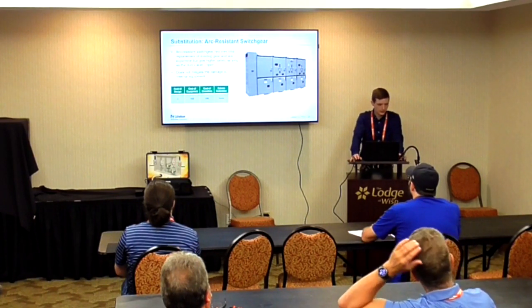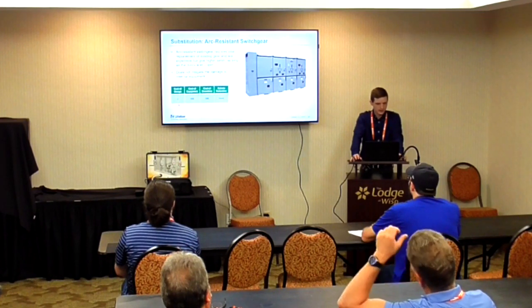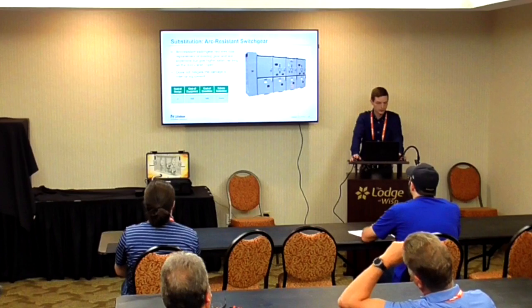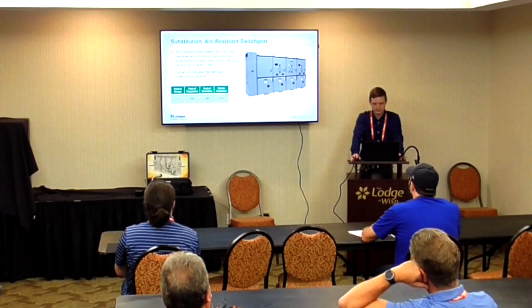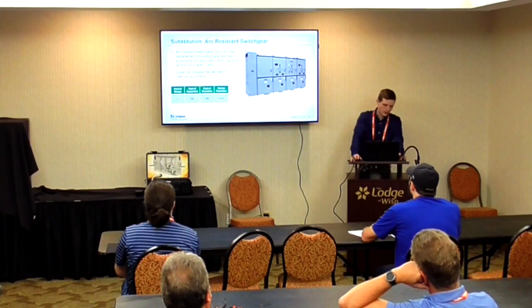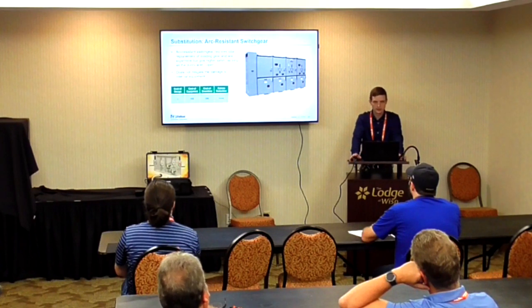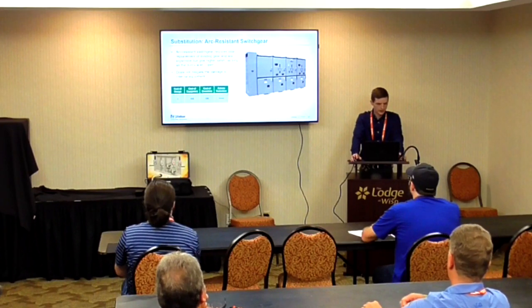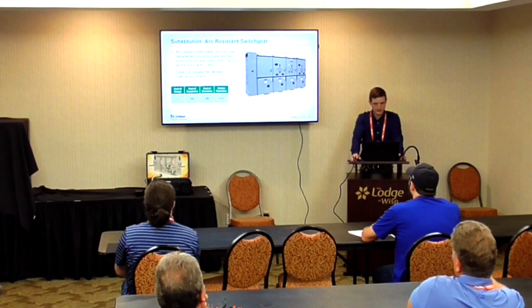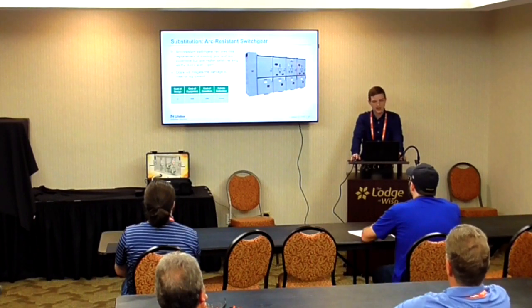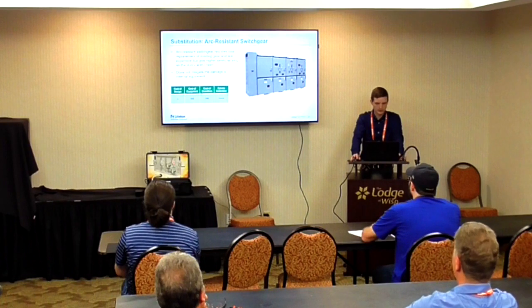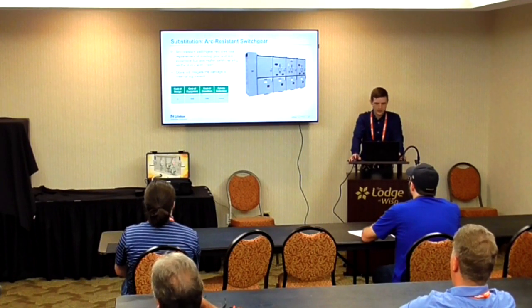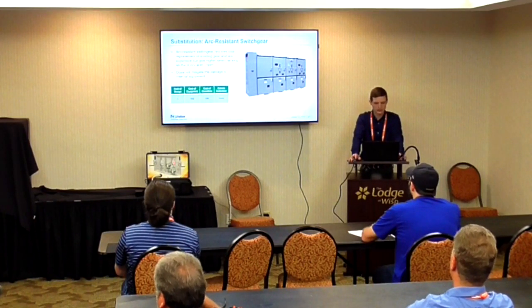The reason why a lot of places do this, though, is that the cost of the design is very low. You're just essentially replacing non-resistant gear with resistant gear. The cost of the equipment can be quite a bit more expensive. I don't have hard numbers for you, but just from anecdotal experience, it's usually about 4 times the cost of non-resistant gear, which is already not cheap. And then the cost of the downtime, so you're going to have to take everything out of here in the event that it's a retrofit, and then put it back in. So this can be a significant downtime. You're looking at several days. And then for the calorie reduction, there is no calorie reduction. You are just redirecting the arc itself.